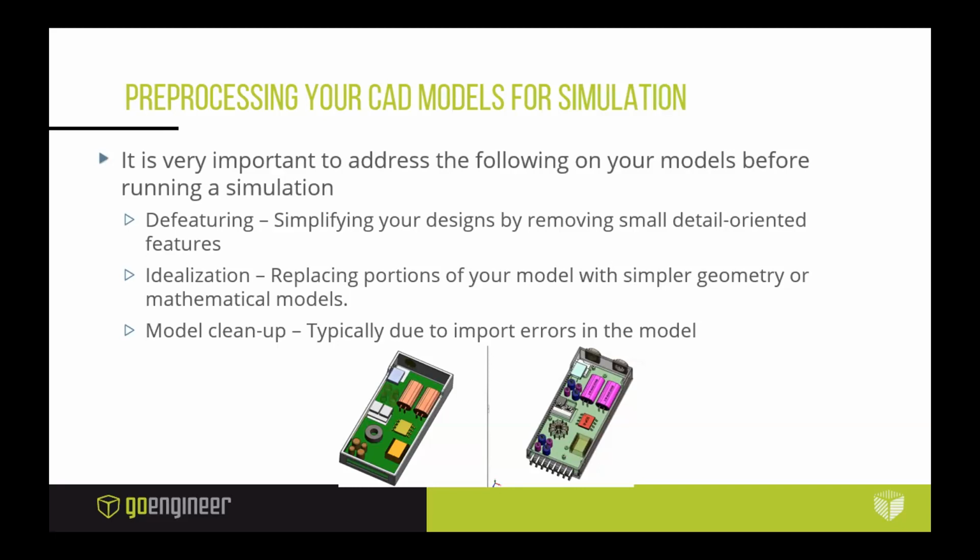And this brings up a good concept that I want to spearhead all this with, and make it your cornerstone when you're doing your simulations: start simple with everything. Start simple with your CAD model that you're using. Start simple with the setup of your simulation. Don't go nuts with setting up everything exactly how you want it to begin with. Start with a standard material, maybe simplified fixturing and constraints and forces, and also a coarser and simpler mesh. Those three things, make them simple, and then slowly start adding more detail to all three.